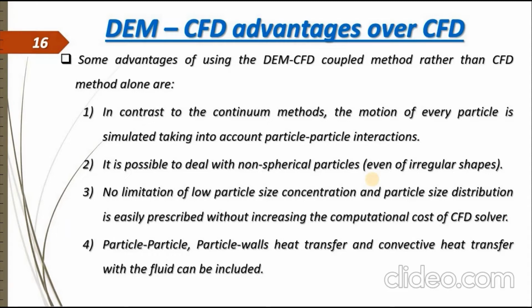There is no limitation of particle concentration, and particle size distribution is easily prescribed without increasing the computational cost of the CFD solver. Also, particle-wall heat transfer and convective heat transfer with the fluid can be included in the DEM-CFD coupled approach rather than the CFD alone approach.